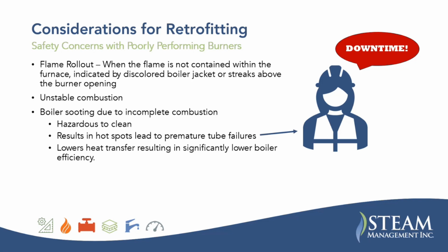If you think about it, soot is basically unburned fuel, and so it is flammable. If you try to clean it yourself, you can create a hazardous condition. There have been instances of operators trying to clean their boiler themselves with a metal wire brush and creating a spark and the soot blowing up in their face. It's also an irritant to your skin. It's just nasty stuff, so it's great to hire a professional to do that.